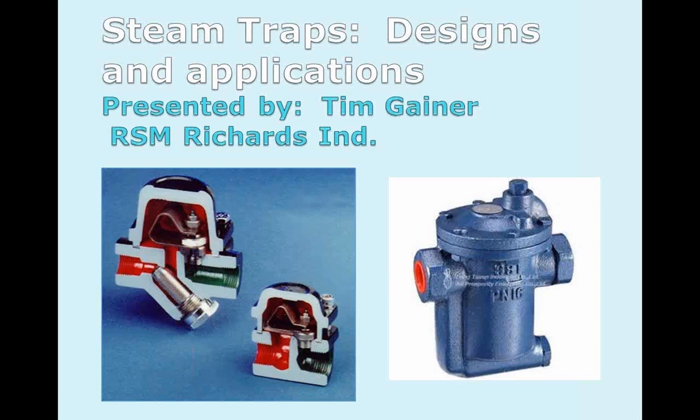A bimetal is decent, and I see a fair amount of float and thermostatics too. But again, as the pressures get higher, I see more of the disc traps and delta elements. I'm thinking more like power plant type pressures where you're getting up into the hundreds, maybe 1,000. There's no one technology for everything, so depending on the pressures in your main, that will vary.